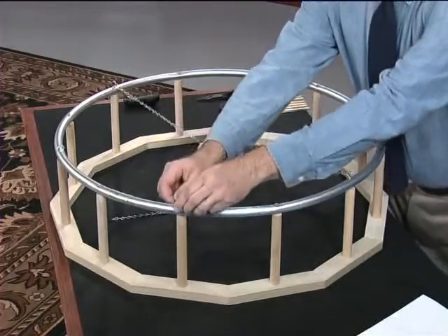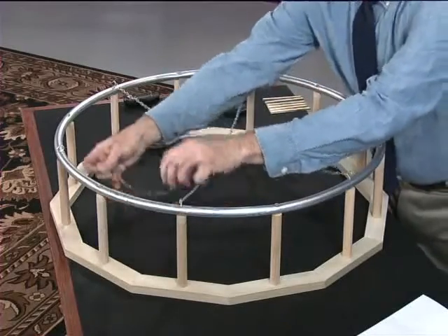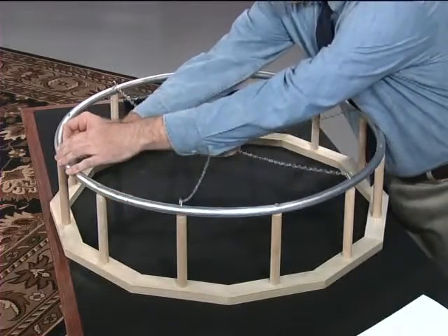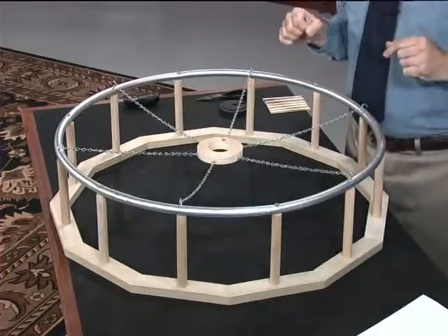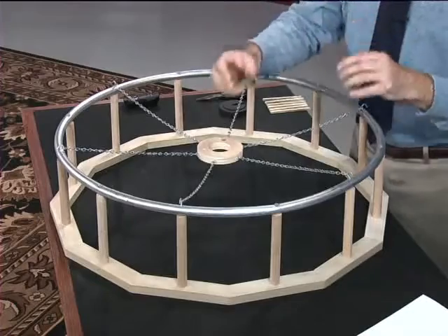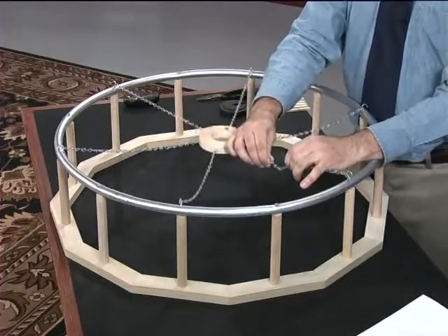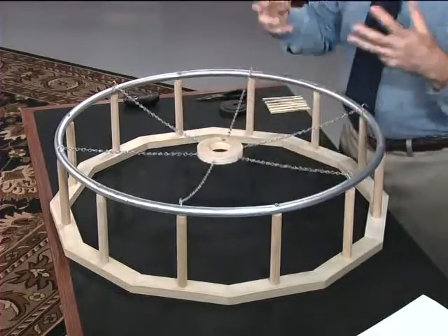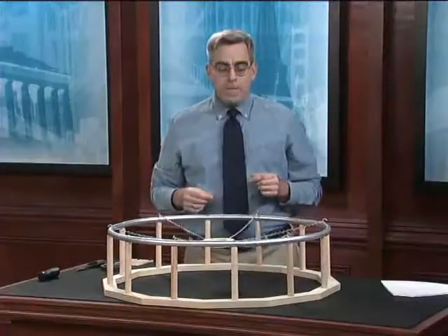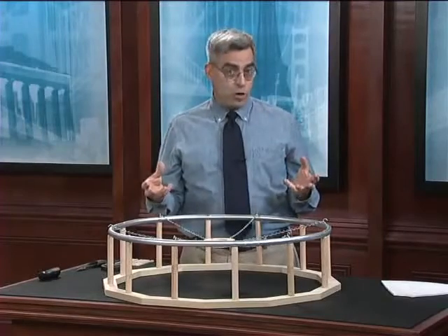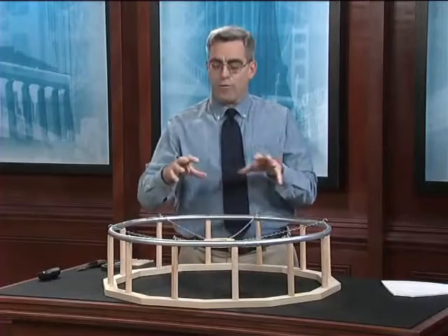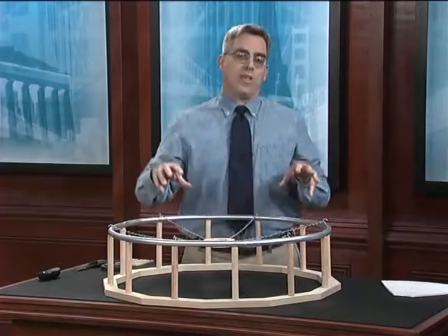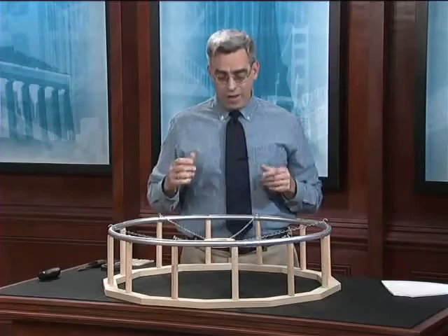The actual cables in Madison Square Garden were steel cables, not chains, but I like to use chains because they are a little bit more visible, because they drape a little bit more nicely, and because they very clearly accentuate the fact that these elements are incapable of carrying any compression whatsoever. They are true tension structures. And so here we have the basic structural system of Madison Square Garden. Now, the actual building used far more cables than this. I've only used 6 here for the sake of simplicity so you can understand the system without too much clutter.